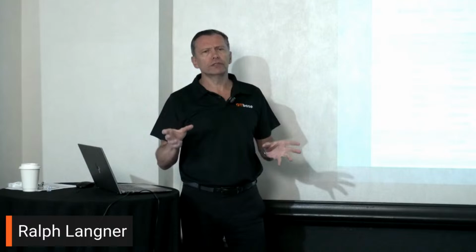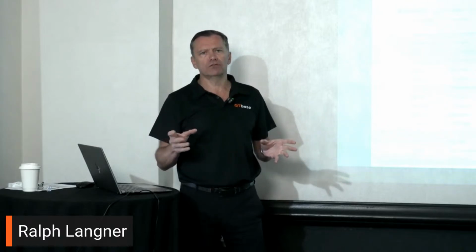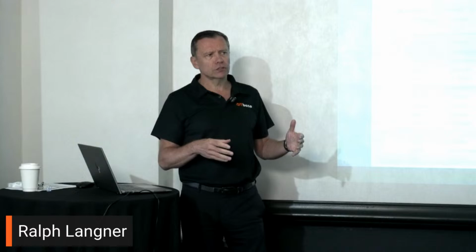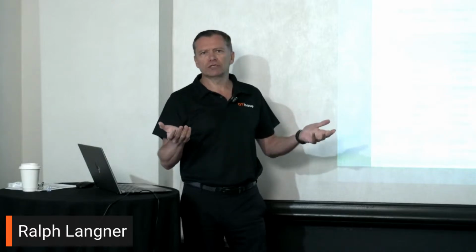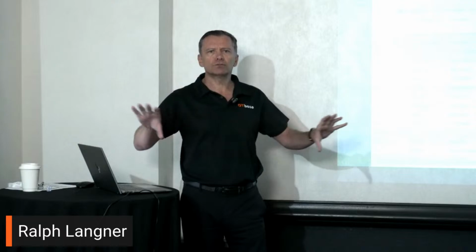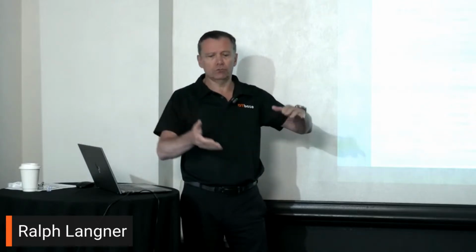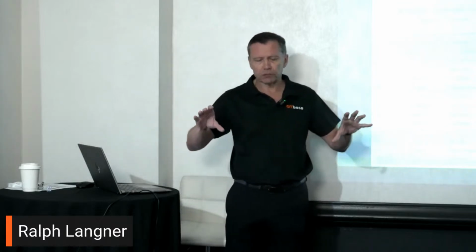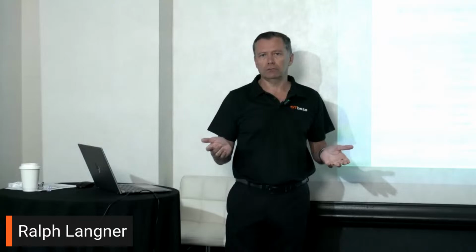So that is not really a good segmentation strategy if you would rely on that model. Because let's just assume for a second you would place all your PLCs in one specific layer that you protect with firewalls, etc. But if that one layer is compromised, that specific zone, if you will, then your whole production is going to go down.